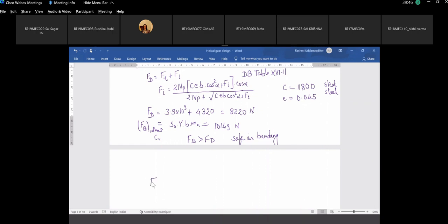So what is the formula for FW? From the design data book, this is again modified for the helical gear. The wear strength would be greater. So this is K, which depends upon the hardness, B, which we know, the diameter for the gear because we are designing for gear, the size factor Q upon cos square of alpha.